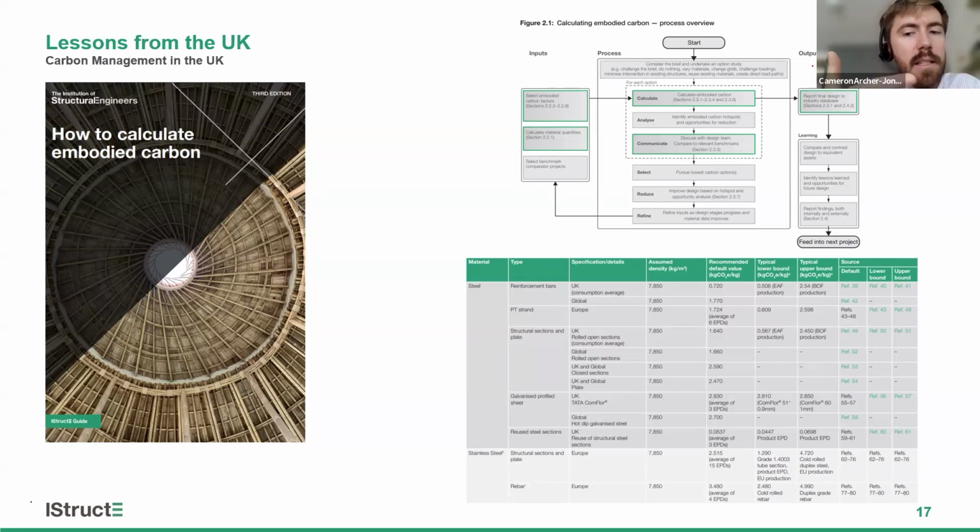It gives a set of useful carbon factors so that if you were on a project, you can complete a defendable carbon assessment at that stage. So the snippet at the bottom there is just one of many sets of tables that have some carbon factors for people to use. And it also covers all those life cycle modules that Lucy presented at the beginning. So it not only covers A1 to 5, it covers the B phases, as well as C as well as D.